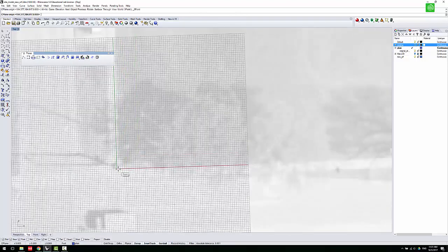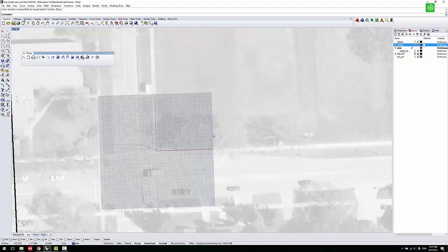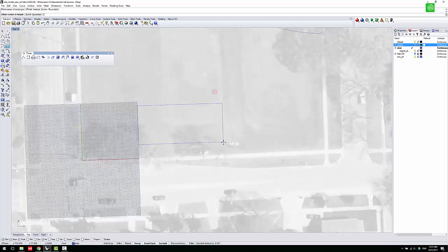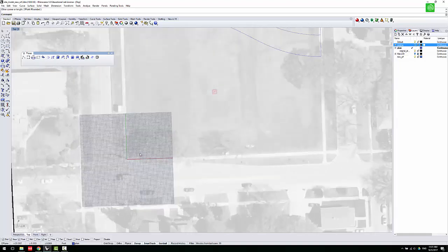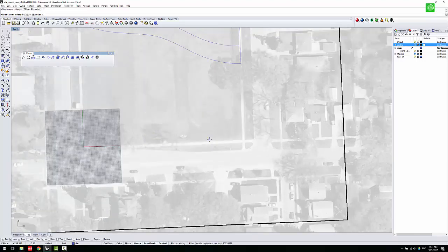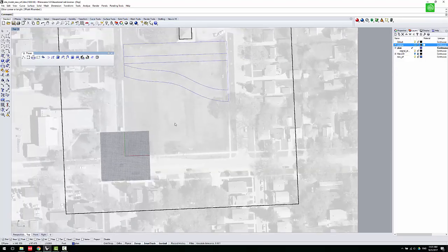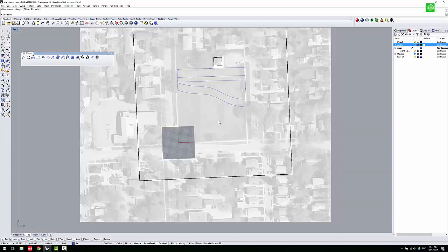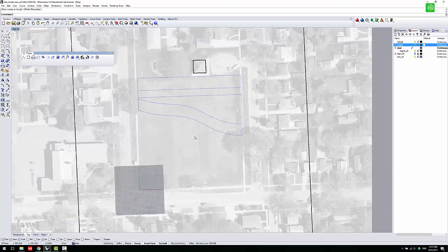And also I set up the coordinates here. You see here I use this 3-point coordinates tool. If I pick here, the coordinates are all going to be the same, which means if I draw squares, they will line up and be parallel with the direction of the sidewalk. If you draw a line and it's not perfectly parallel with each other, you should use this 3-point C-plane tool to set up the coordinate system. Just Google it if you don't know how to do that, all right?